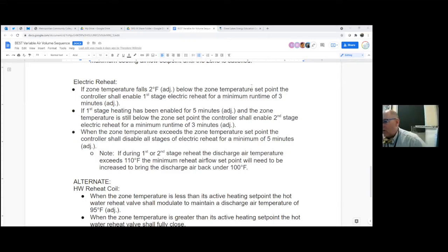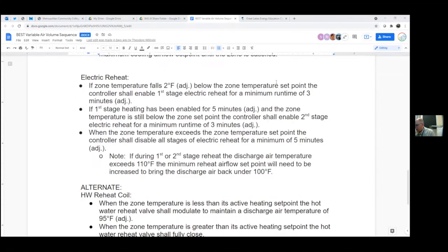I don't know for sure what it is. It's actually going to be on a case-by-case basis for that particular room. You have to meet whatever your state code is. Once upon a time, it was a certain number of CFM per person in that space. Quite often that equated to around, I think, 1 air change an hour, roughly. Somewhere on the order of 1 or 2 CFM per square foot, 20% opening.